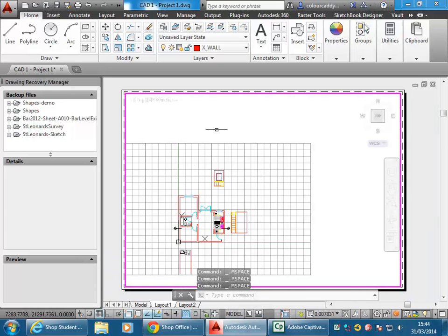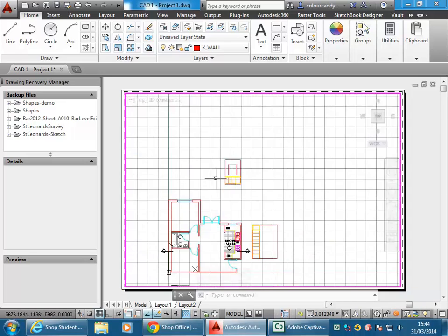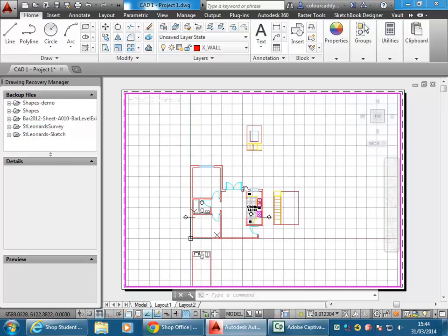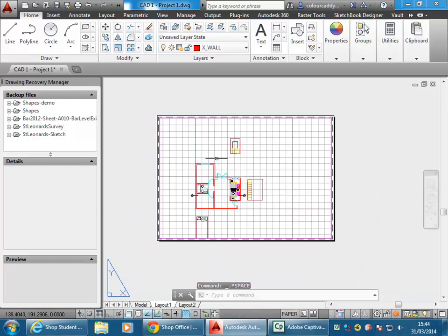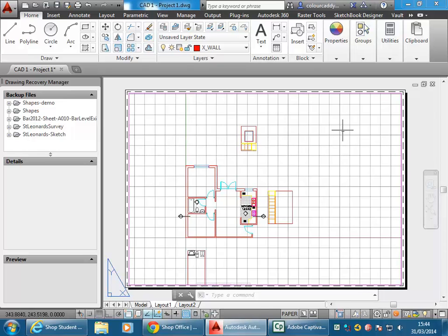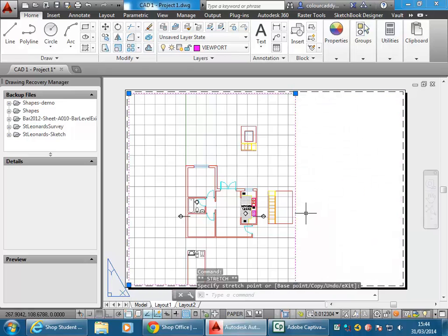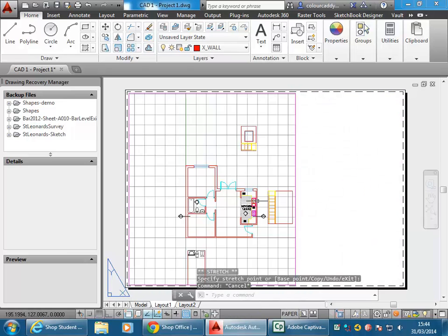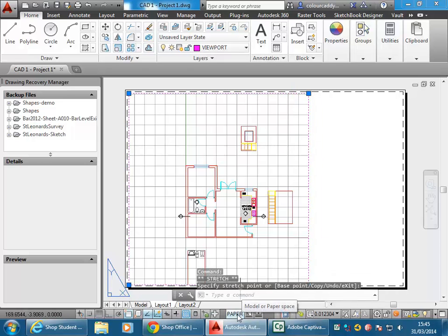And then when you're in model, you'll see that as you zoom, you're zooming only inside that viewport. Pan, anything else that you do normally is just in the view. If I go back to paper, then when I pan and zoom, I'm doing it on the whole page. So the viewport is, we realised already, a view into our virtual model space. And we can have that viewport any size. In paper, I can select the viewport border so that I can adjust it. It's on the page, so then I work on that in paper mode.